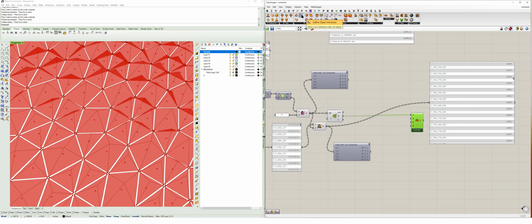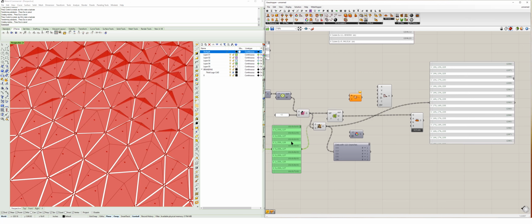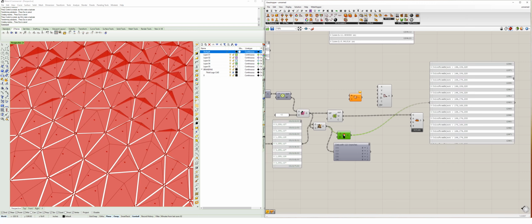Attributes, you can get that by defining attributes. We're also going to define a color, and we're going to define a layer to go on. The colors that we're going to define are simply the input RGB values. And that's going to give me Elefront compatible colors. I'm going to place those colors into my attributes right here. And then finally the layer, I'm going to plug into the L input here. And I'm going to give it a name.